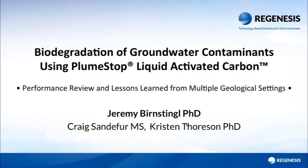We try to avoid that, but sometimes it happens. Then the black carbon that's been spilt on asphalt from the PlumeStop will not come off with a jet wash on day 1. So the PlumeStop that's stuck onto the soil is not going to move. If you imagine the PlumeStop moving through the formation and being mobile for the 1 to 3 months, the trail that it leaves will be stuck. The moving front will continue to move, so we have to look at how far the groundwater will move within 1 to 3 months.